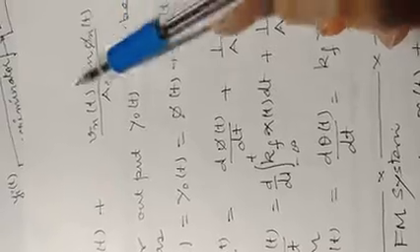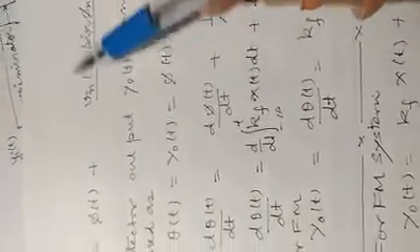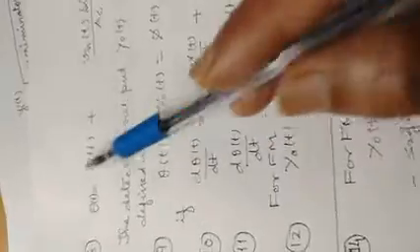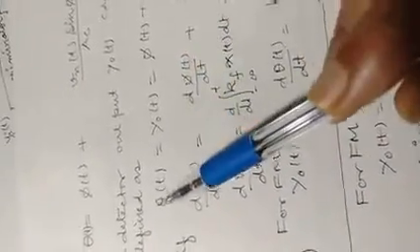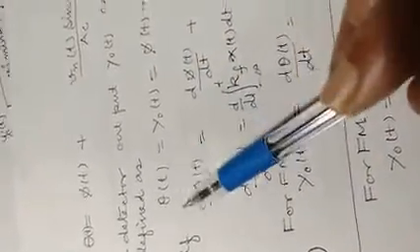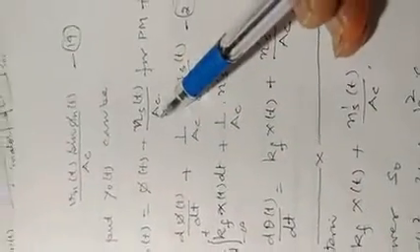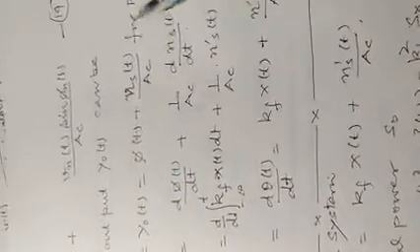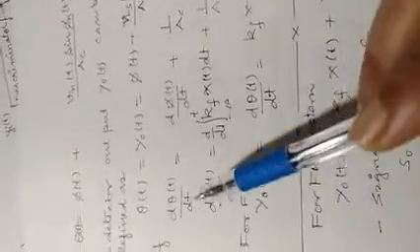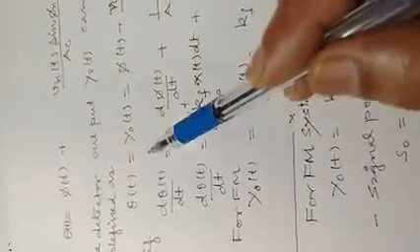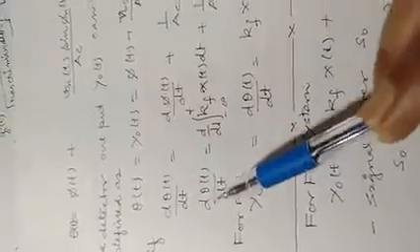And this V_n of t sin phi_n of t is nothing but the quadrature phase component of the noise. So we are writing theta of t, which is the output of the detector. So theta of t is equal to y_o of t is equal to phi of t plus n_s of t divided by A_C, where we replace this value with the quadrature component. This will be used for the phase modulation, and if we differentiate this as a whole, then we'll get it for frequency modulation.